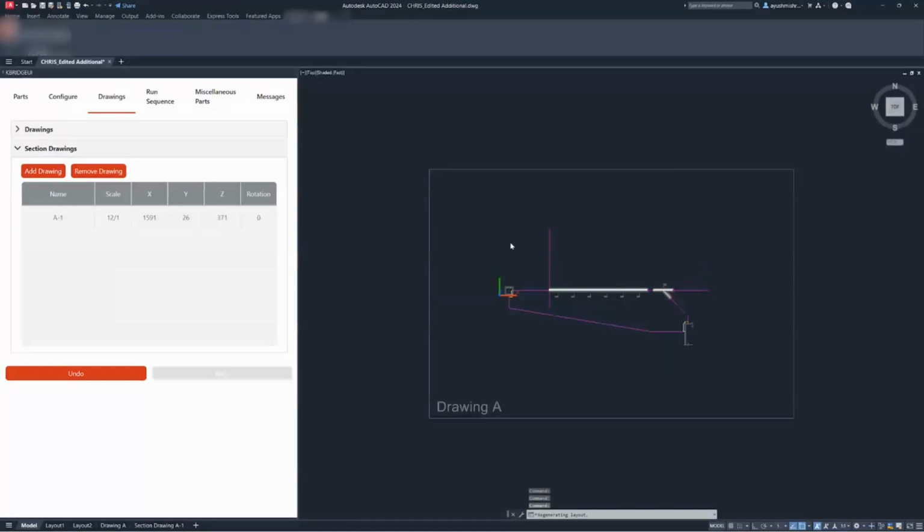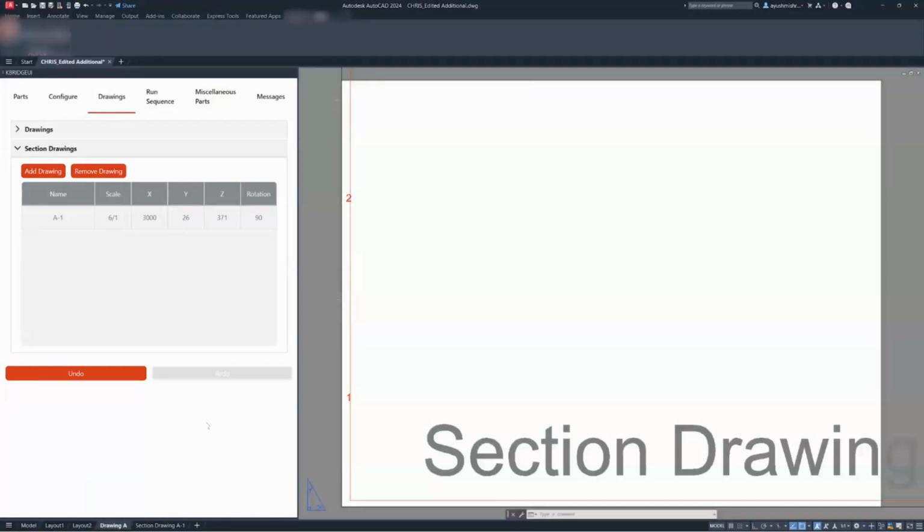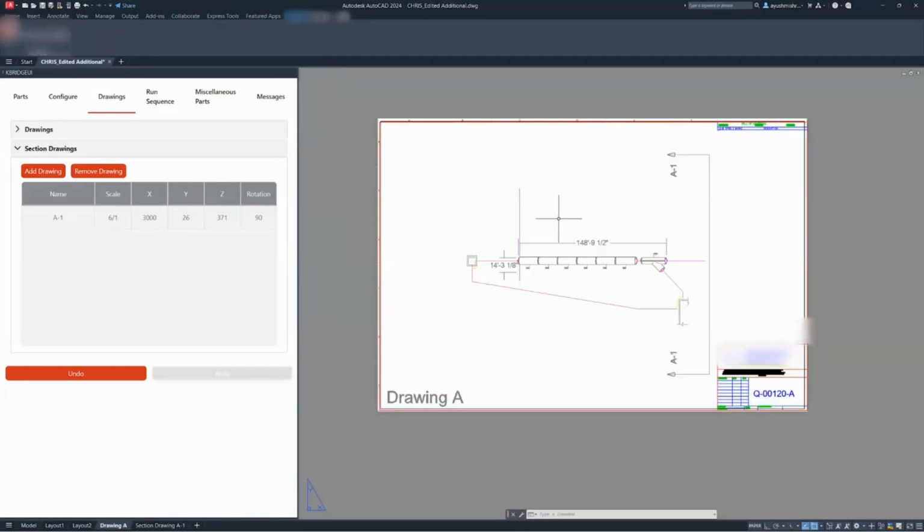And now I can create drawings of the pipe pieces that we've created so far, inclusive of section drawings. So that might be important, again, depending upon where I am or what I need to show to gain ultimate approval. These drawings can be used for everything from engineering to installation. Even the way this is set up is for the sequence of pipe, the order in which you would actually install them. So there are a number of things that happen here. Holland's adding a section view here to show just from a different view what we need to show. We can change everything from scale, of course, to the right viewpoints and decide what content is shown in each drawing. And then here are the drawings that are created.